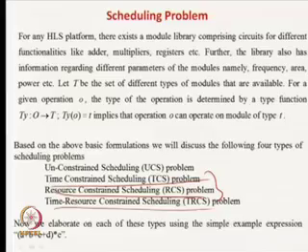So, this is the most practical scheduling problem. In most of the cases we use resource and time constrained scheduling problems, because we say that I have to do all the operations in so and so many time steps, and this is the maximum number of resources, you cannot have anything more than that.